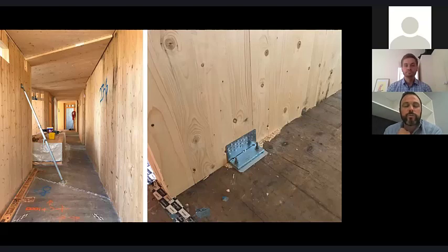We worked very closely with Vistek, who did an exceptional job with this, that allowed us to remove a lot of what you traditionally see in these types of structures with the brackets, and to run these screw connections. Now, every job's different. Earthquake loadings and general loading needs to be considered. But what Vistek did on this was really simple and worked really efficiently, even down to every screw at that connection being the same screw. They just increased the centres as you went up the building and the load reduced. And that large bracket was a more intense bracket needed on certain shear walls on both ends, strategically located where your acoustic wall needed to be.